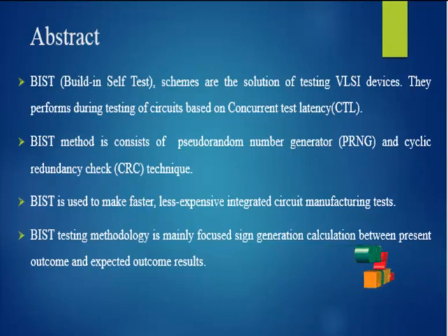First we build the BIST concepts to detect the wear-out and identify the locations of faulty cells. Next, the physical location of failure sites within the SRAM. Many faults in the site from different mechanisms result in exactly the same electrical fail signatures, and the probability for each wear-out mechanism is estimated by the matching algorithms following the BIST and the failure rate distributions.